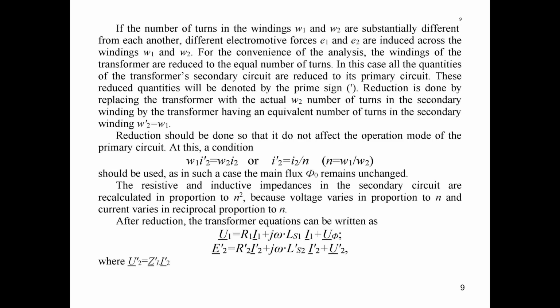And here the resistance and inductive impedances of the secondary circuit will be recalculated in proportion to n to the power 2, where n is W1 over W2.